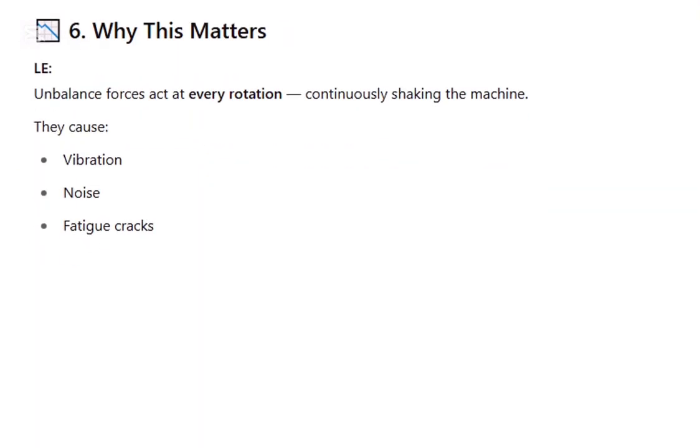Why this matters? The unbalanced force acts at every rotation, continuously shaking the machine. Vibration, noise, fatigue cracks.